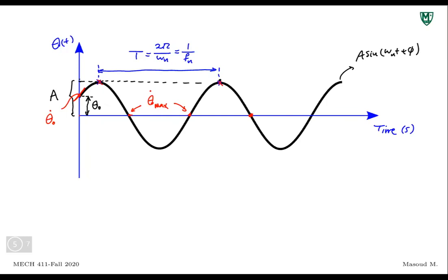And there is one more thing that physically makes less sense, but if you're looking for phi, as Dominic said on this graph, you can just extend this, and this distance here gives you phi over omega n. Sorry, phi over omega n. It's the initial phase for this motion. It's more about the signal, meaning that that's how far we are from theta equals 0.